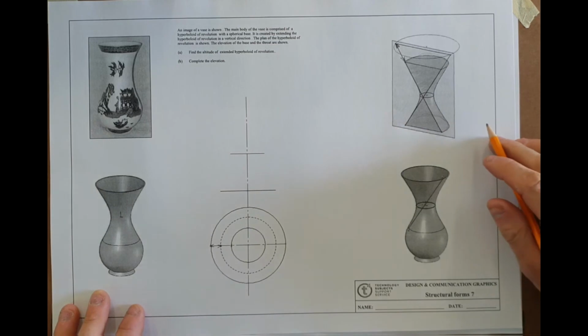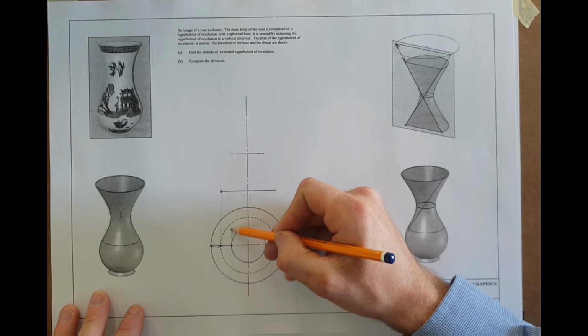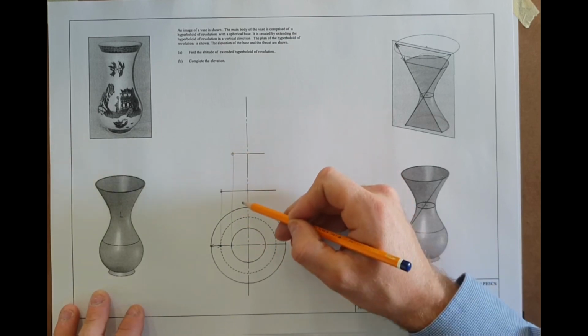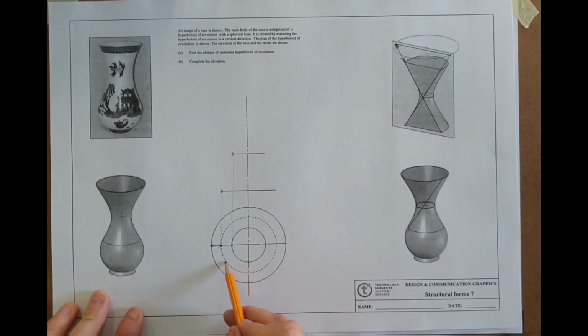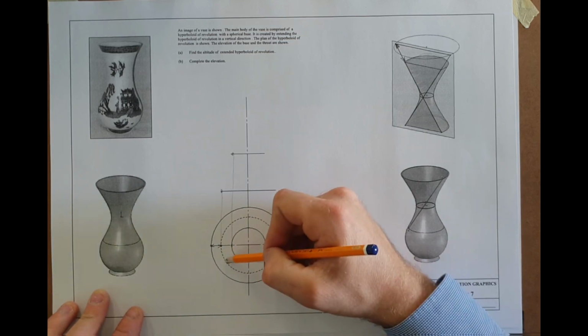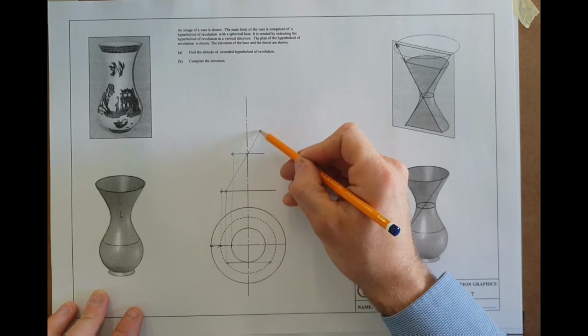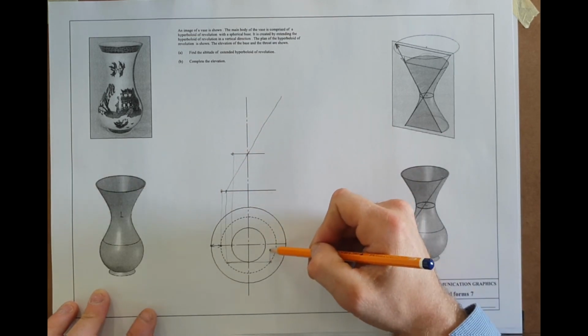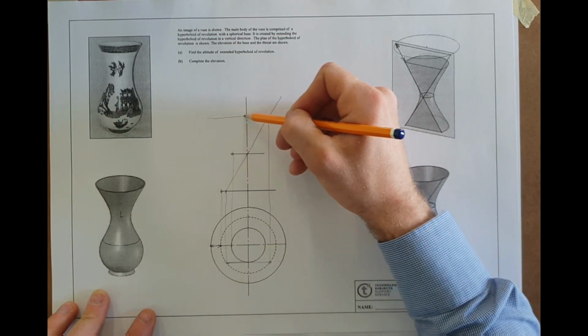So I want you to give it a go yourself. How do you start it? Oh, that's the base circle, given. That's the throat circle, given. Where do you start though? Can you find a set of elements, the true length elements that go from the base to the throat to the top, the original top, before you extend out to the new top? So the original one here is from the base through the throat up to the top, which is here, which gives you the height.